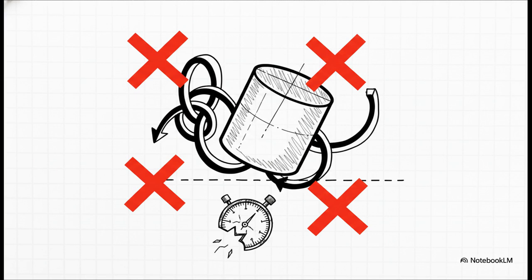Second, and this is a massive pet peeve for many experienced engineers, putting datums directly on theoretical centerlines instead of actual physical features. You cannot mount a theoretical centerline on a physical spindle. The datum has to be derived from a physical surface. Third, confusing circularity and runout, or just ignoring the rotational function entirely. Fourth, and this is crucial, misinterpreting indicator readings. Inspectors often mistakenly read the total indicator variation, or TIR, and confuse it with a simple radius check, accidentally halving or doubling the intended tolerance and incorrectly passing or failing critical components. And finally, confusing material condition modifiers, which just introduces total ambiguity into the inspection process.